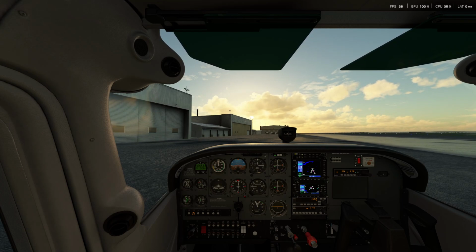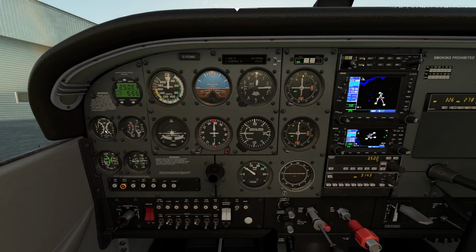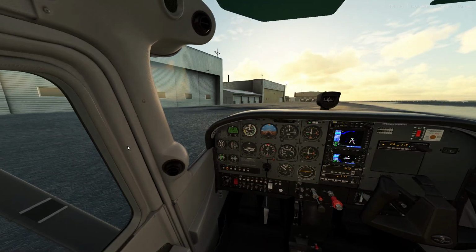Alright, sweet, so I'll bring it back to about 1000 RPM. And then we'll start the engine run-up checklist here. Alright, so the parking brake is set, passenger seats upright, seatbelts checked and secured, flight controls full left, full right, full left, full forward, check free. Fuel quantity, that's over here on the left side, is 56 gallons, 53 usable. So that's checked, mixture, full rich.